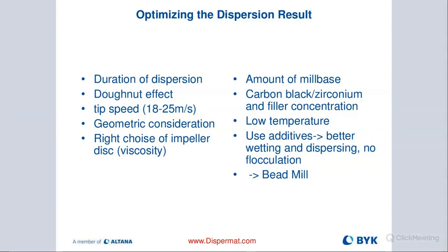So ideally, you should stay within the 50% range. Also, if you're milling after the pre-dispersion with the basket mill, you don't want to have too much product in the container, or the weight of the basket mill would cause the product to just spill as soon as you apply any type of shear force and increase the tip speed.